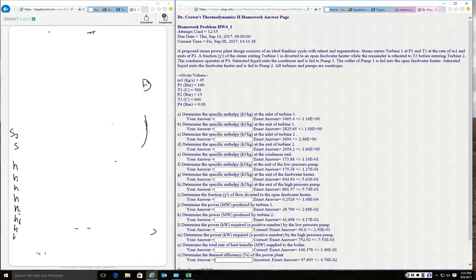And let's start with turbine 1. The general equation is dE_CV/dt equals Q dot minus W dot plus, it would normally be summation m dot i, but since we have one inlet and one exit, m dot times (h inlet plus V inlet squared over 2 plus g z inlet minus h exit plus V exit squared over 2 plus g z exit), since we have the same mass flow rate at the inlet and the exit.